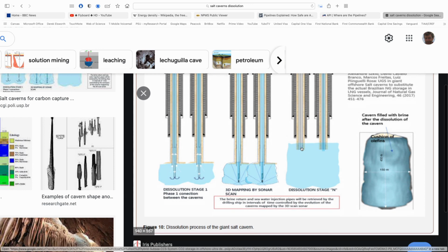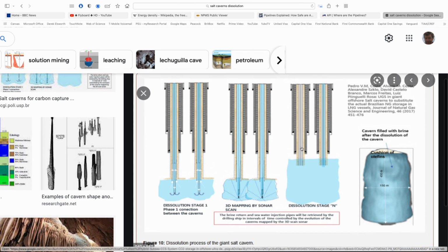Then you use that to store either pressurized natural gas or hydrocarbons. In Scandinavia, they actually excavate caverns. They don't have salt, they have granites, wonderful but very hard rock, and then they store oil in them, in the subsurface. They typically have what's called a water curtain, so that outside the cavern, they have water under pressure, so that the only flow is from the high pressure injection points into the cavern, and so if water is flowing into the cavern, oil can't flow out.